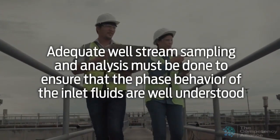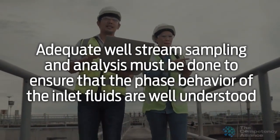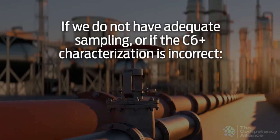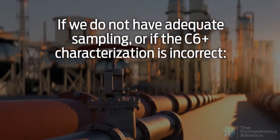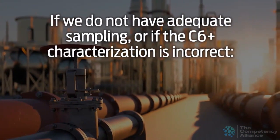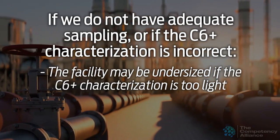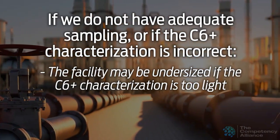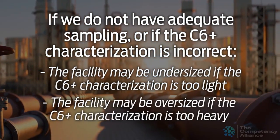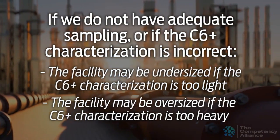Adequate well stream sampling and analysis must be done to ensure that the phase behavior of the inlet fluids is well understood. If we do not have adequate sampling, or if the C6+ characterization that is used for the facility design is incorrect, the risk becomes that the facility may be undersized for liquids handling if the C6+ characterization is too light, or possibly much too large if the C6+ characterization is too heavy.